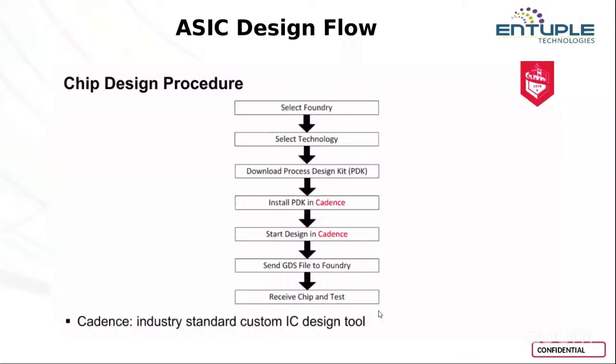Right. So we have various EDA tools. In ASIC design, particularly for Cadence, we have various tools available for ASIC design in both the full custom mode as well as the semi custom mode, right? For full custom, we start with the schematic editor, and the design rule checks are there, and the simulator.